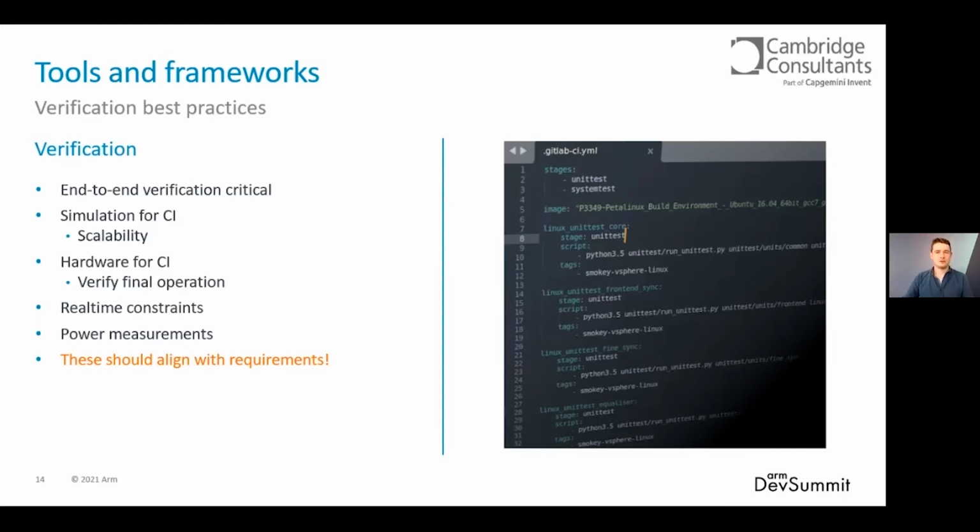End-to-end verification of the model's functionality is critical to ensure that once the model has been deployed, its accuracy still meets the requirements. The verification must be set up to demonstrate that all of the pieces of software and hardware, from sensor inputs to results, maintain the accuracy requirements set out at the start of the project. Critically important here is that the accuracy of the deployed neural network is measured by including all of the data pre-processing and post-processing blocks too.